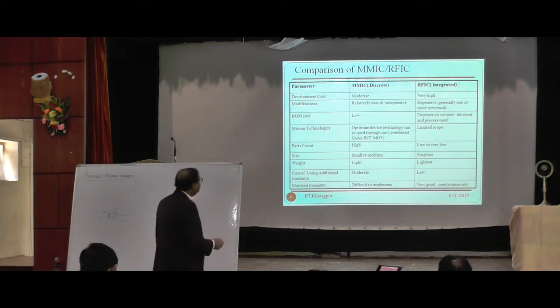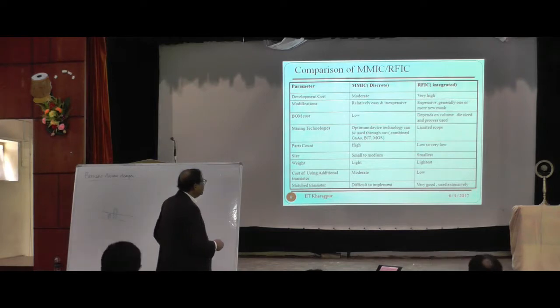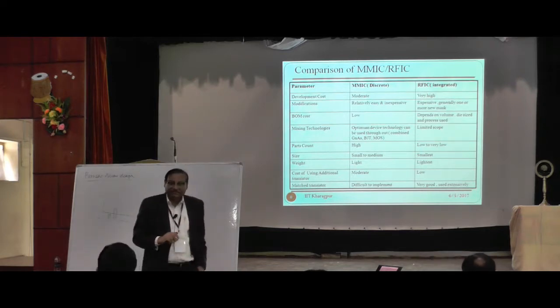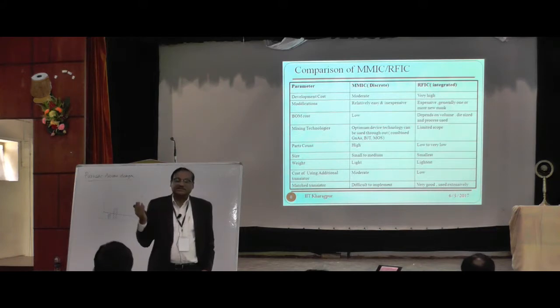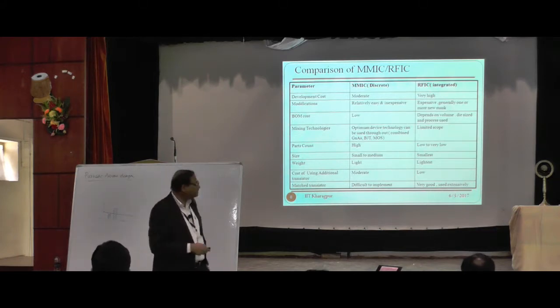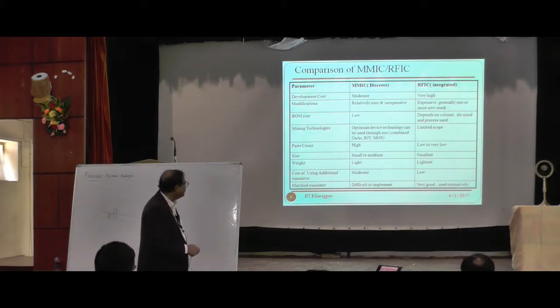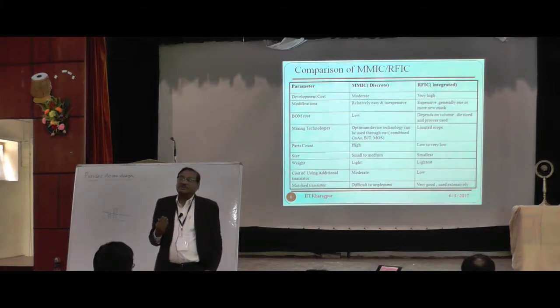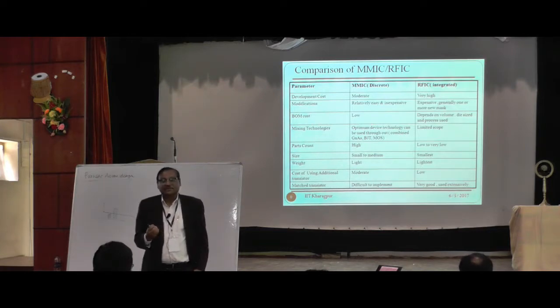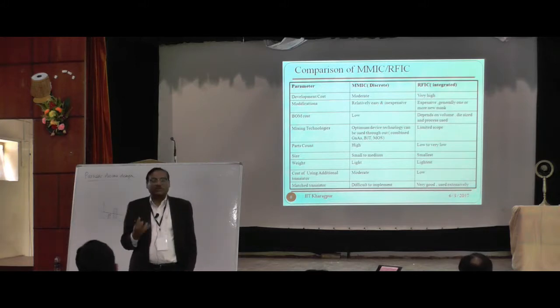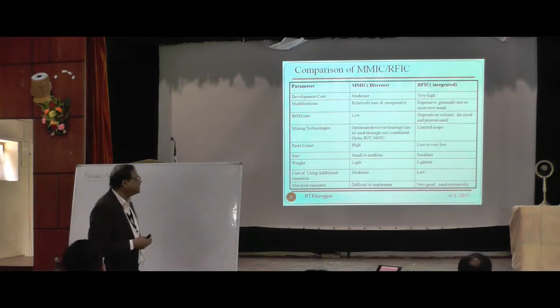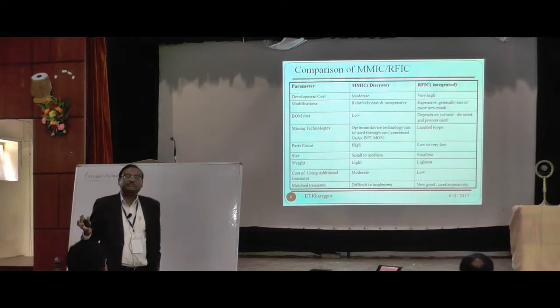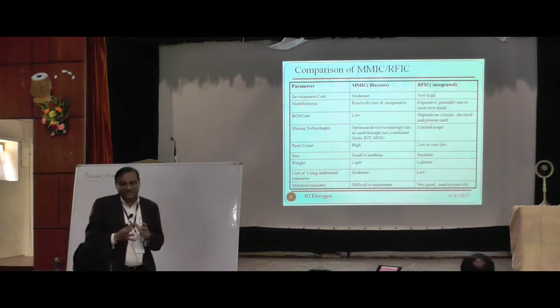But if you look at the RFIC, the development cost is very high. But once this is developed, the fabrication is in millions. So the cost will be lower, right? And the scalability is much higher. Then it is lightest, low power, and so on. So these are the advantages. So that's why the RFIC is becoming so popular nowadays, utilizing the advantage of modern silicon technology, where MMIC is now gradually going to very specialized applications, where the frequency range is very high, where the area is not so important.